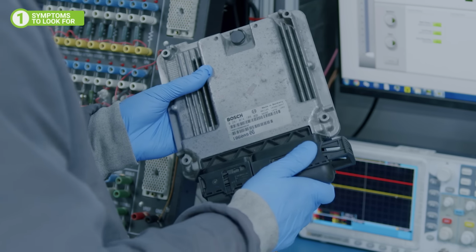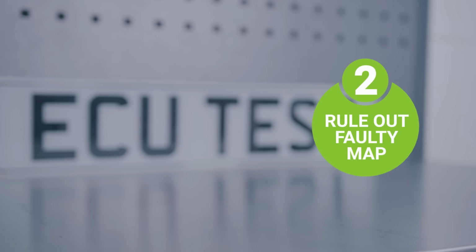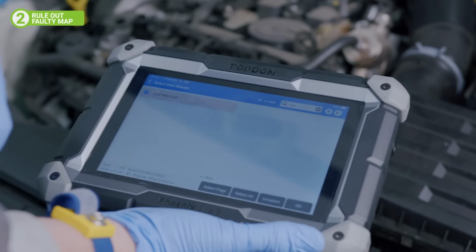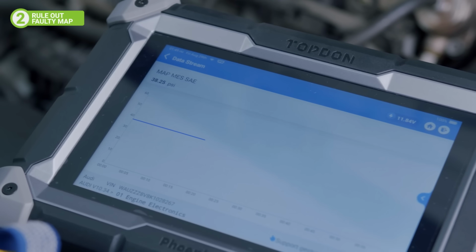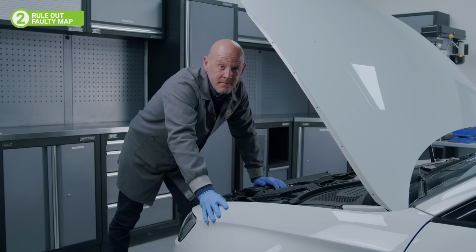But for now, let's get into the diagnosis. First and foremost, you should check live MAP readings with a diagnostic scan tool. You should see steady readings that change promptly with throttle input. If readings are stuck, erratic, or unresponsive, that's a strong indicator of a fault.